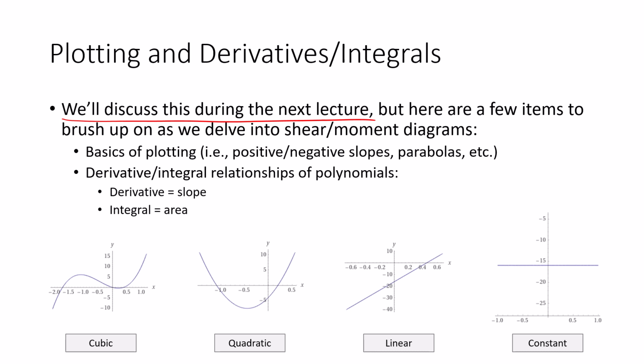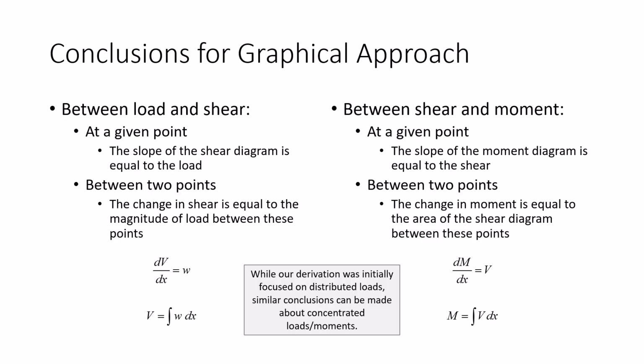Well, what we're trying to do is work backwards. We're trying to go from load to shear to moment. So we're going to be integrating. As long as you understand those patterns, that's really all you need. For our graphical approach, we can utilize our derivative and integral relationships to make some pretty straightforward conclusions.